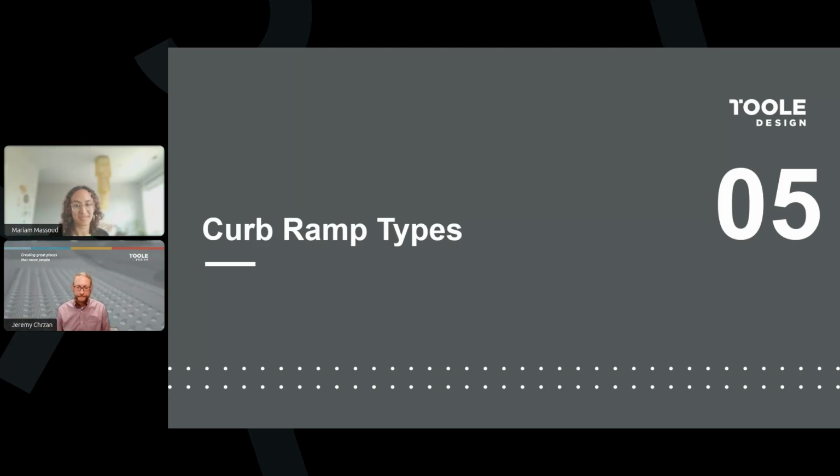Let's see here. There's more. The standard slope on ODOT combination curb and gutters is 12 to 1, 8.3%. How would someone make this work with the 5% max gutter street slope? I think it essentially requires warping the gutter. Okay. All right. Very good.